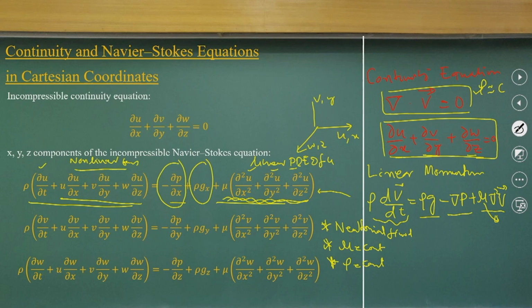So, you just have to interpret these equations. This is the vector form, and if I write in the x direction, I will have a local acceleration and the convective acceleration, which has the nonlinear terms, a pressure gradient, and the gravity force components. I can look at whether the gravity force dominates in the flow field I am considering, and whether the viscosity dominates. All these terms I have to look at to see which are dominant. How can I simplify these equations?